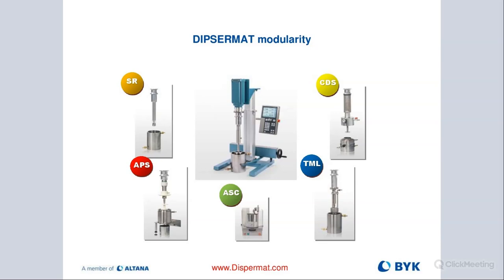That takes the air out of our formula. And if you think about it, like the air entrapped in a mill base, these are tiny air bubbles. And look at it this way, they could be almost like little air mattresses, and they buffer the blow of the beads when we are milling. And by removing them, I have more energy that I can apply to my pigment or my particle. And that basically gives me improved milling efficiency. So some people really like to mill under vacuum.